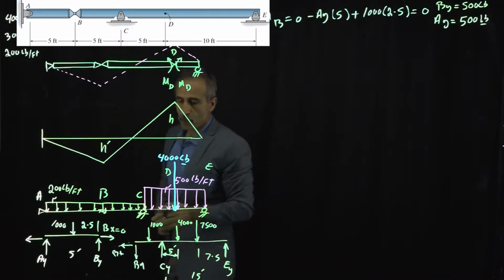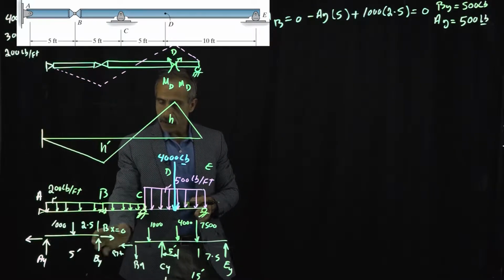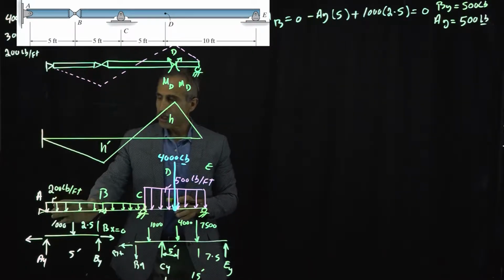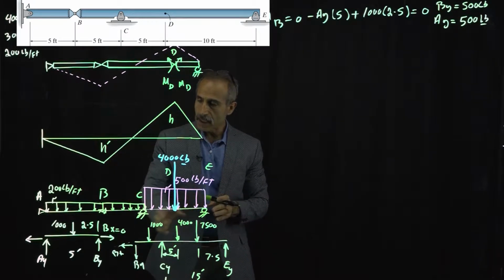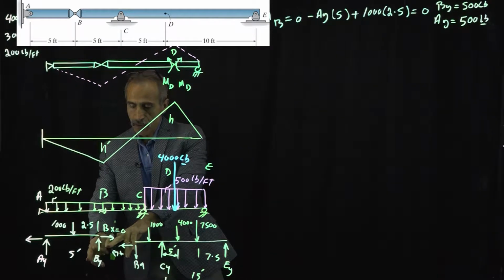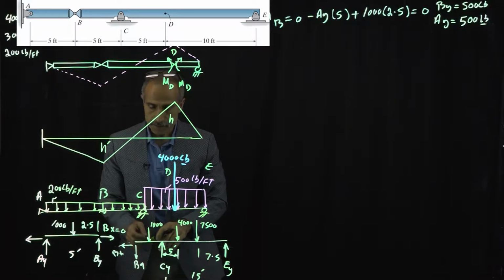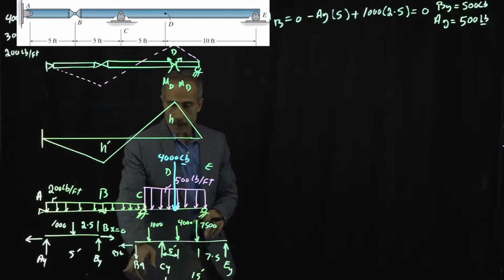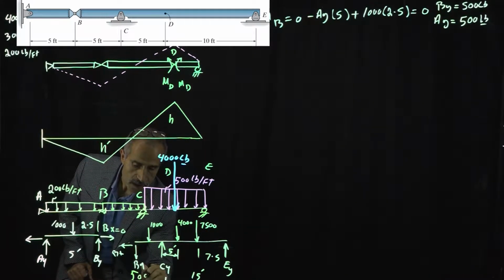Now we have that. We have more equations than reactions, so we bring this up to this side of the beam. What we did is first analyze member AB, and then when you come back to BE, these reaction forces are going to be opposite with the same magnitude on this side. And we can go ahead and calculate this. So BY is 500 here, and it's going down.